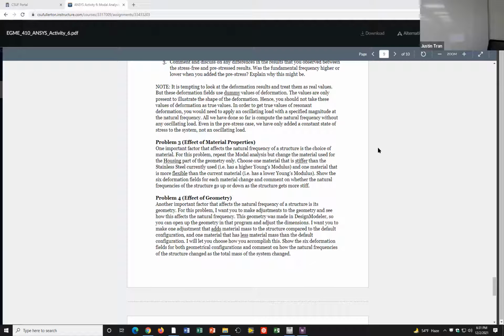If you look at the frequency of the earthquake, the earthquake frequency is much lower than whatever you're designing. When things start vibrating, you're always focused on the low frequencies where they can start vibrating. So whatever that frequency is, it should be much lower than the natural frequency.